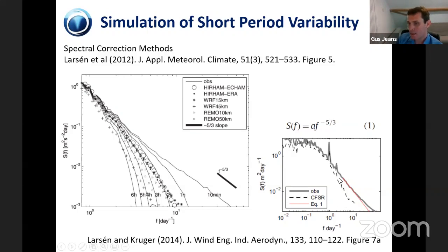So what I'm trying to get out here is that this is a quite different approach from the method I've just outlined before in the Metocean report, where you find the long-term sort of 2 hour, 3 hour effective wind speed from the model, and then convert it to equivalent 10-minute or 3-second gust values. Here, these methods are looking at ways of correcting the spectra from the models to better represent the measurements.